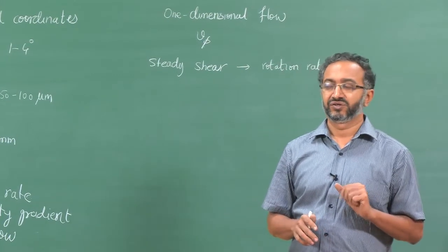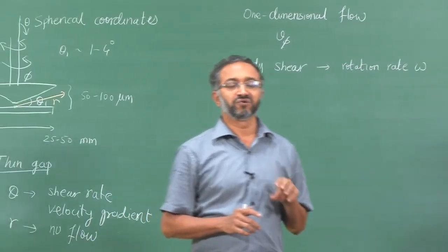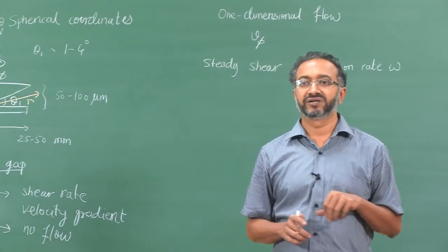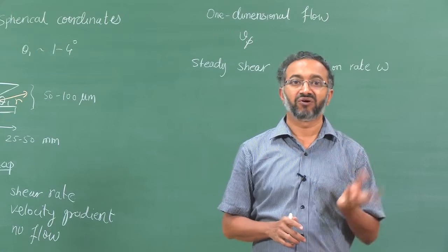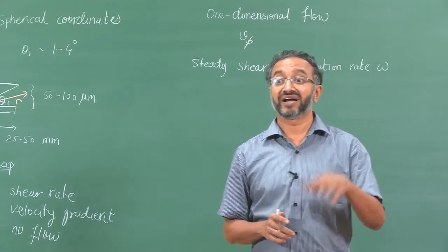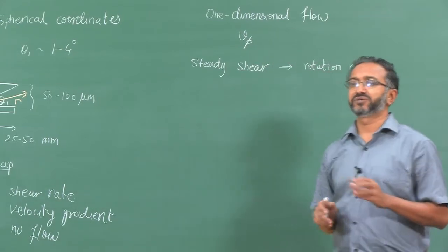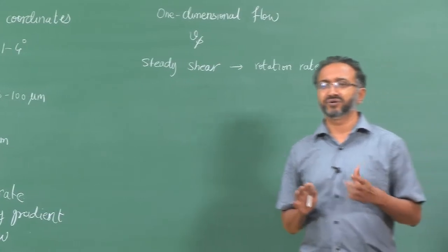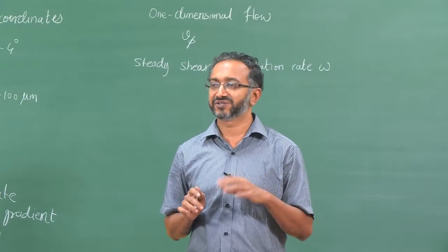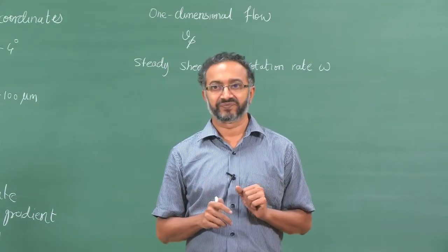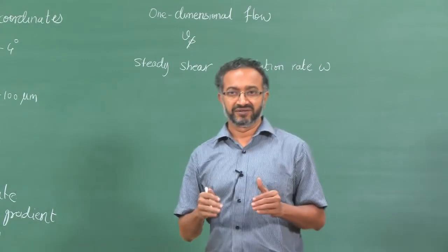So, the question is, if I am rotating the cone alone, can I expect the fluid to only move in the rotational motion and not have the radial component, or no matter how careful I am, will there always be a radial component and therefore I have to ignore it? So, these are the two questions, right. Is it possible for me to be very careful and then say that I do not really need to assume that radial velocity will be 0? Under normal circumstances I can assume that radial velocity will be 0. So, what do you feel among these two, which one is more reasonable?